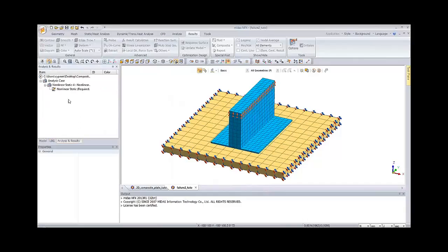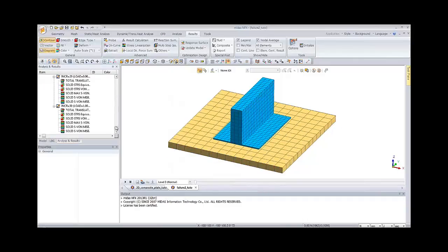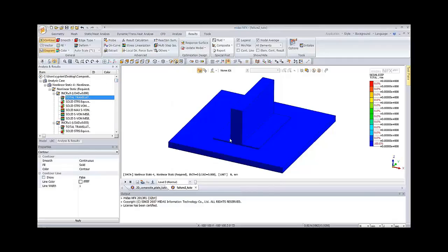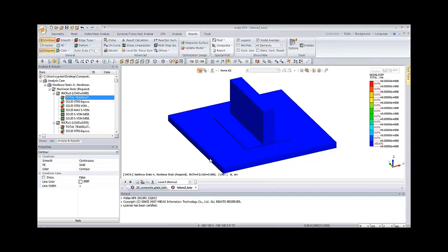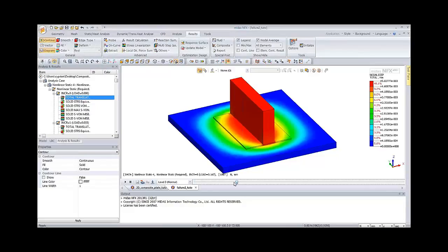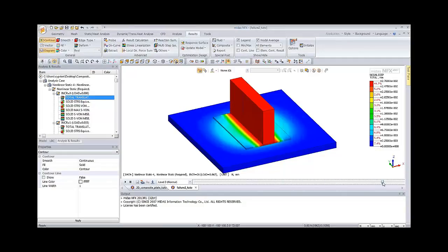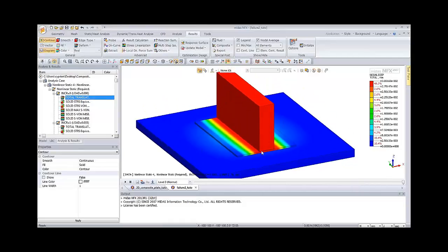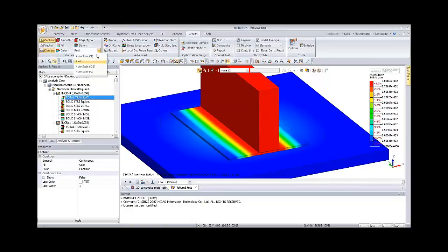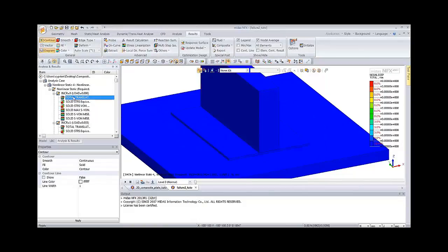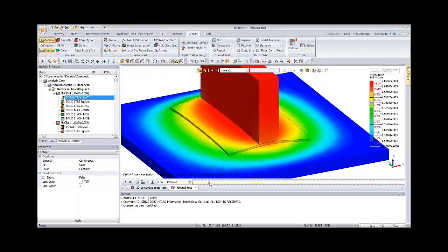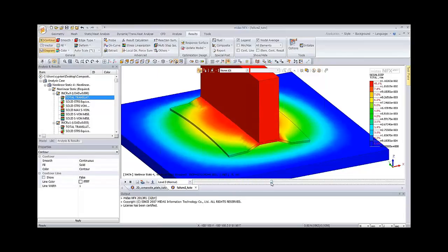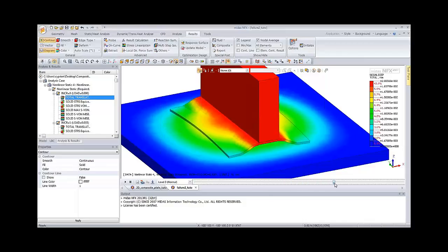So first of all, the displacement. I will put first to real, so it gives me something like that. So this is a nonlinear static analysis. So when I go through the steps, you see the form of the behavior is changing. It's difficult to see, so I will increase the scale and come back to the beginning. So you see from there, when the analysis continues, the contact is breaking with the plate, and finally I have something like that. So there's a space between the two,